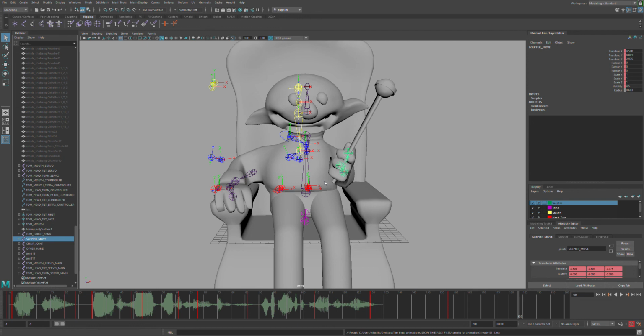Therefore, this is basically how you take a file from Maya and use the rotation data from the joints and convert it into data recognized by servos, using min and max values in the animation converter.